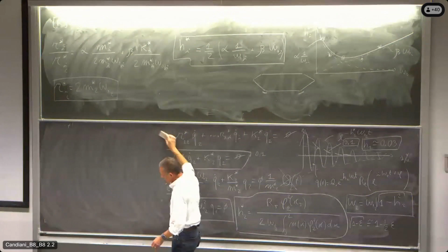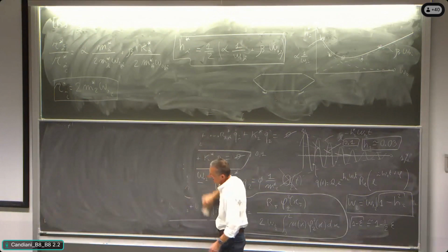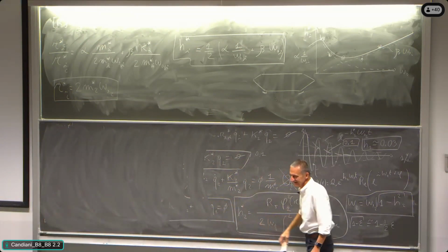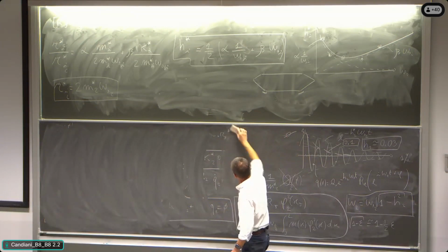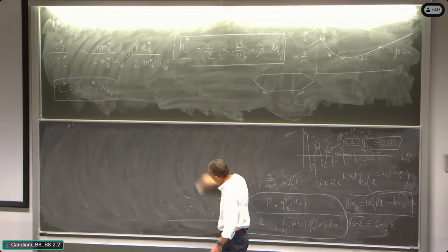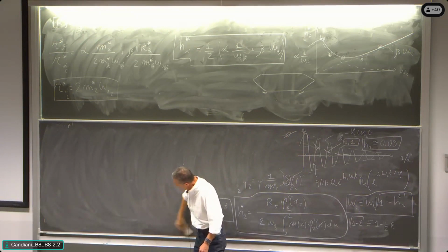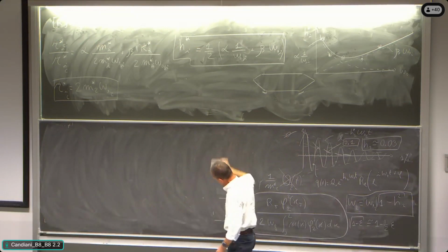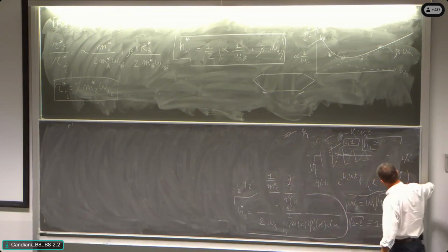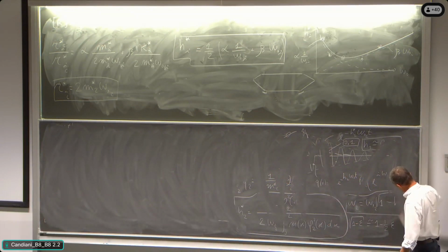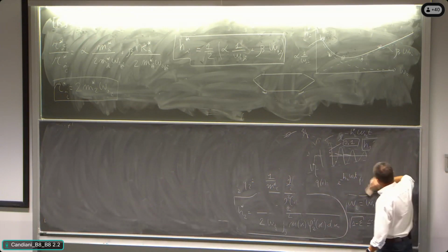So the expected non-dimensional damping of the Messina Strait Bridge is less than 0.3%. So in the calculation we must assume 3/1000 by the Eurocode, but the expected could be less.